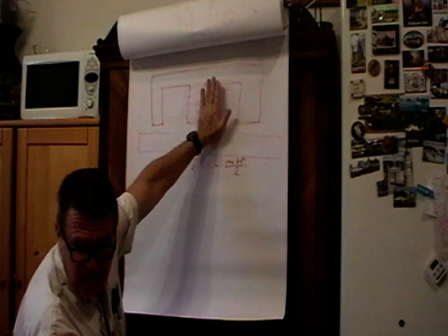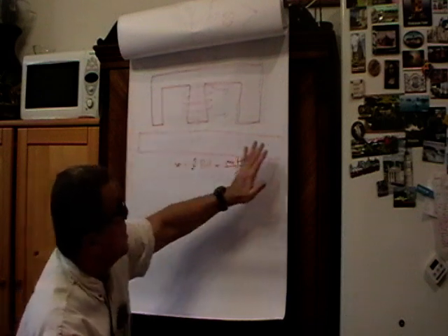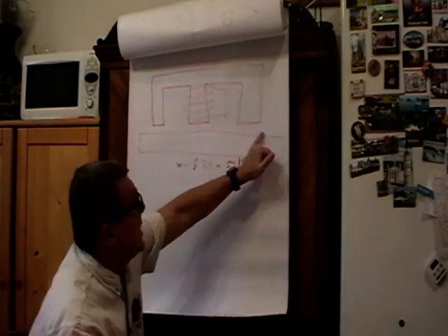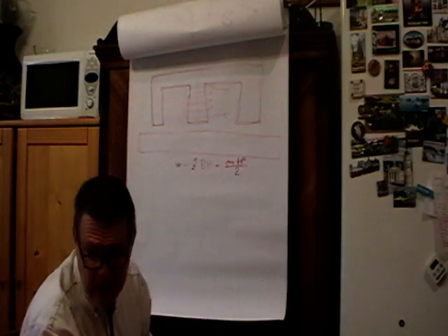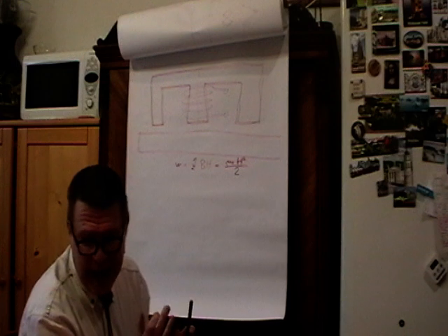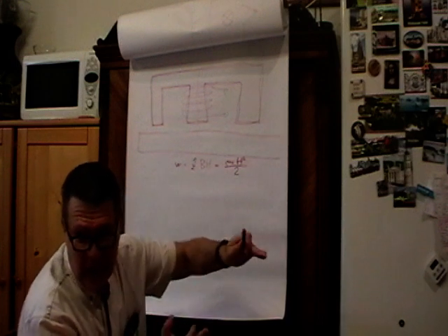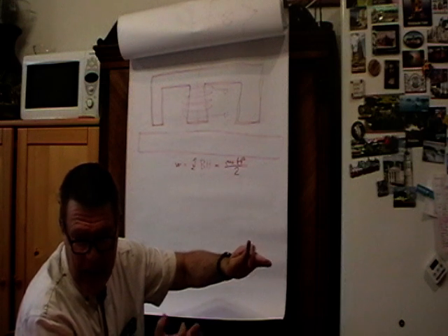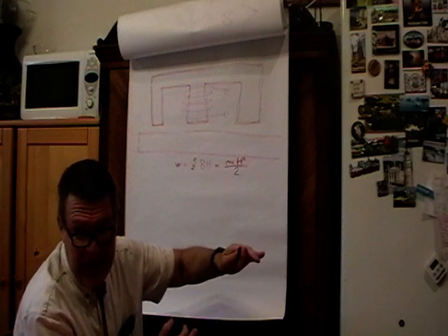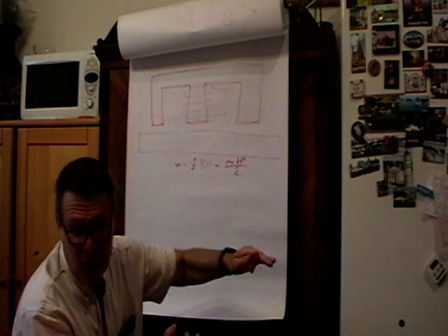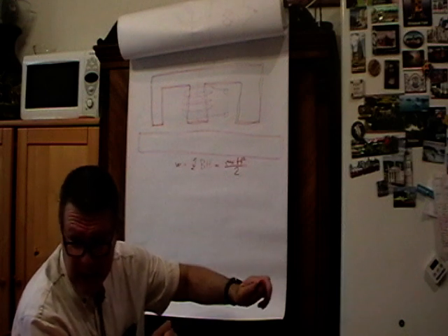The magnetic circuit would not change very much, but it would change here in the air gap. How would it change? Well, in fact, the movement would decrease the gap, and the energy that has been in that part of the gap would change into mechanical work.